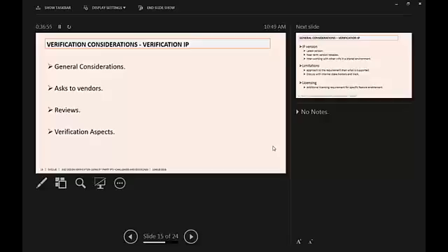Exactly. So if the IP can be power gated, you need to also know the latency requirements when you wake that system up. So these wake-up mechanisms and all those things you may have already built in, but you may have to plan some glue logic. You have some requirements at the SoC, with a power controller and the other blocks, so you may have to plan a glue logic. That's exactly where we talked about the glue logic requirement that you have to evaluate.